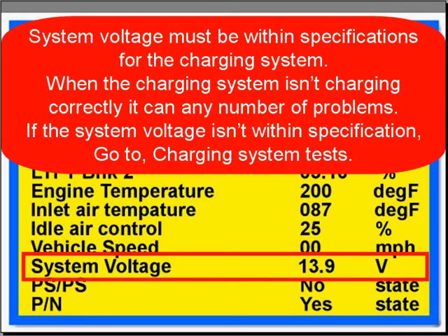System voltage is very important. It must be within specifications. When the charging system isn't charging correctly, it can cause any number of problems. If the system voltage isn't within specifications, go to Charging System Test.